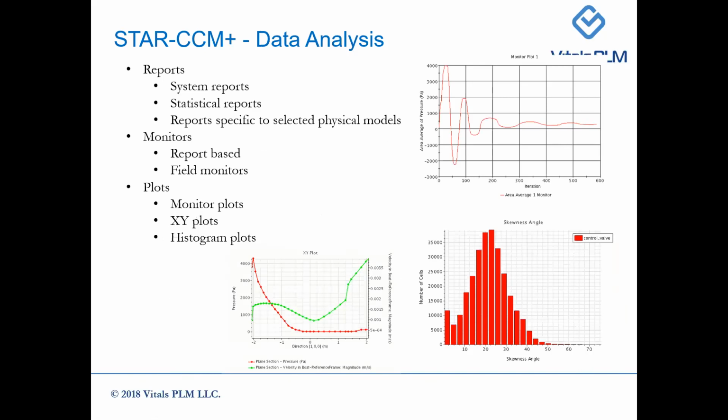For data analysis, we can generate multiple reports like system reports, statistical reports, and reports specific to some selected physical models like emissions or chemical reactions. And we can monitor these reports using monitors, and we can write our own field monitors.